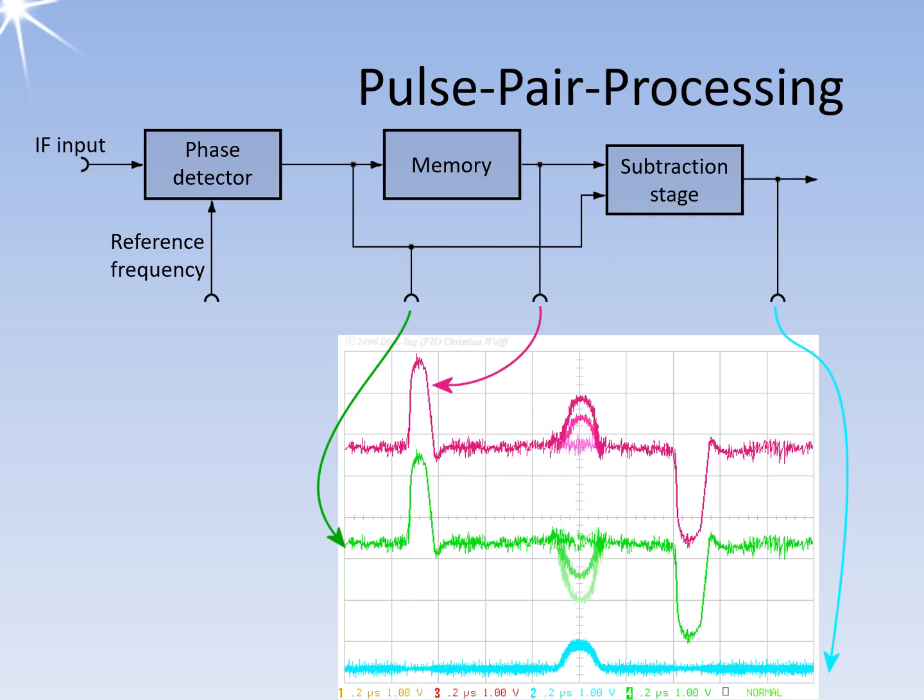A Doppler frequency can be measured quite accurately by the rate of change of the phase position of the echo signal. To do this, the echo signals from two or more pulse periods must be compared. The complete procedure is given the name moving target indication, MTI. The pulse pair processing is only a part of it. The whole process is part of the radar signal processing. However, this pulse pair processing can also be performed digitally on the computer.